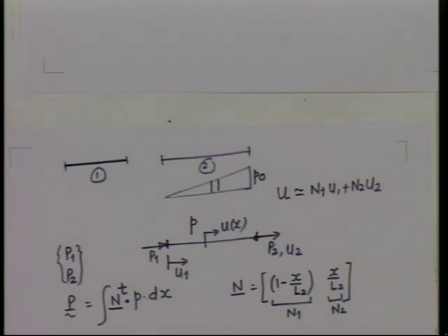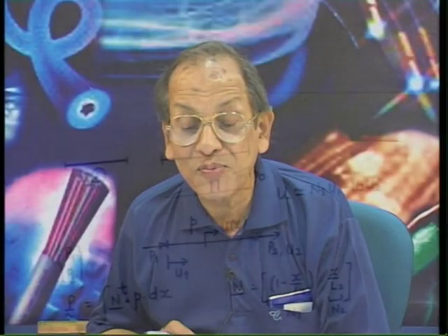If it varies non-linearly, we have a second order differential equation, and the exact solution will be non-linear. We can also take a quadratic element for this, sir. You can take, then it will be different. You can take a quadratic element, but the quadratic element may not see this problem.